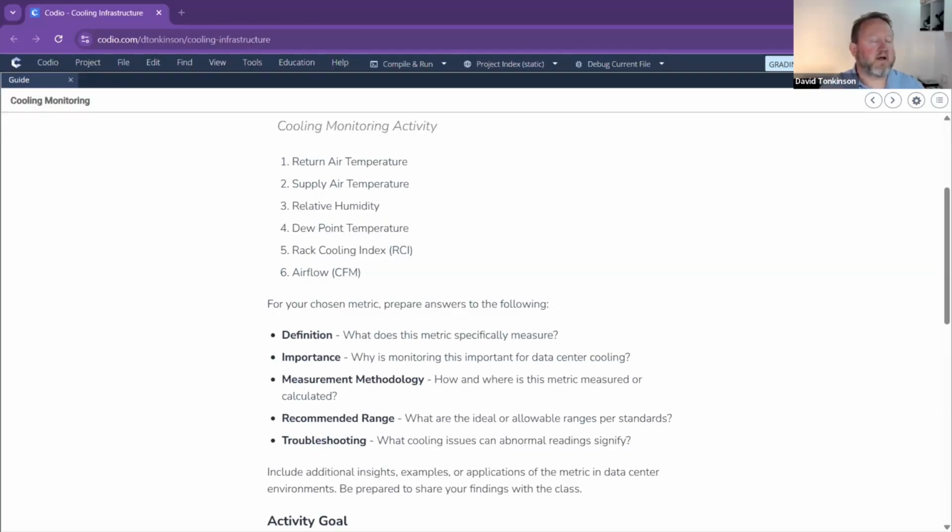So Danielle, to answer that, high humidity. If your humidity is high, there's a lot of moisture in the air, potentially. It's a bit like being abroad. You get a lot of moisture in the air. In a data center, that means moisture will potentially form on cold areas of your data center. We don't want that to form because it will basically mean you will get liquid on your servers dripping from places, and that's not what we're after.